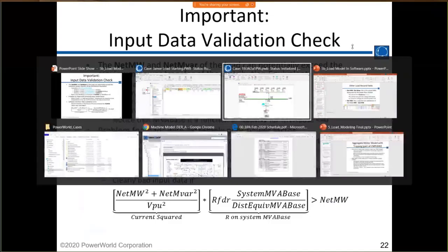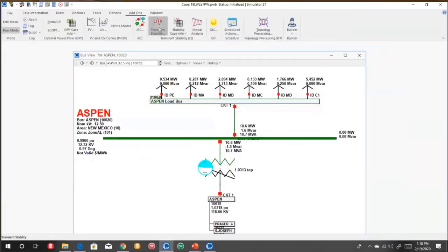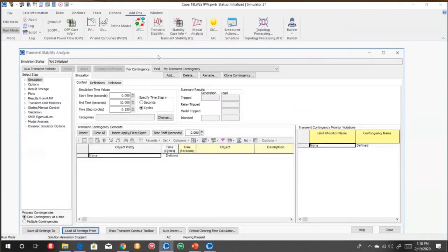So what happened initially in the software tools is you guys get your data from WECC. WECC staff would just go in and clean all this up, because they'd run it, PSLF would crash, and then they'd go in and say, okay, well, this load doesn't belong to the distribution equivalent anymore. And they'd just get rid of all the errors for you. But of course, as soon as you start messing with your case, you would run into the problems. They were just hiding it from you.